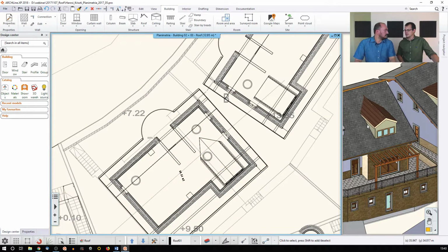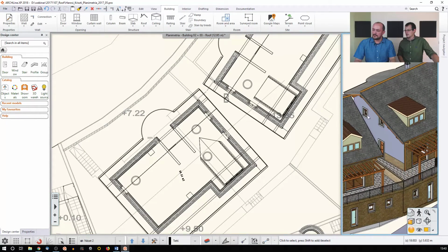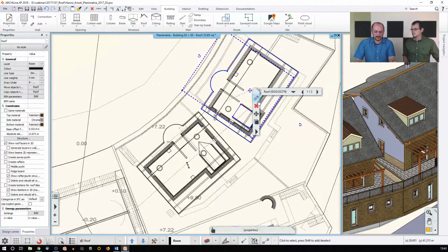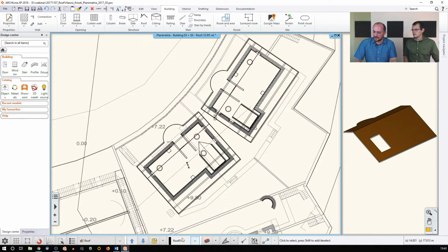Now, this is what I get. The whole point here is that the software is making all the connections between these structures. If I select this, which is the roof itself, and make a quick cut like last time, I can demonstrate what happens under the roof. See, there is a hole under it. The Dormer Roof automatically cuts everything under it from the roof structure, so you can actually use it when you intersect it. It's a habitable area. So it's actually part of the parametric model, a living, breathing part of it.